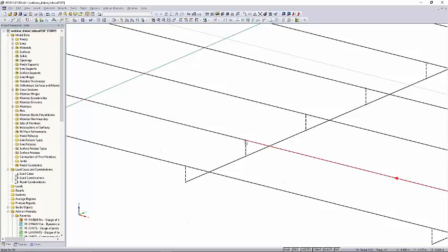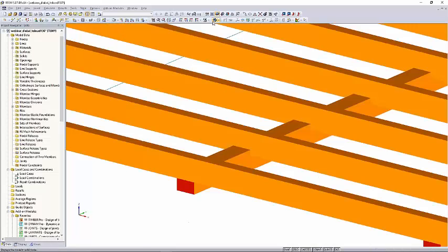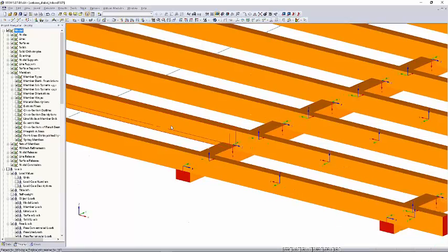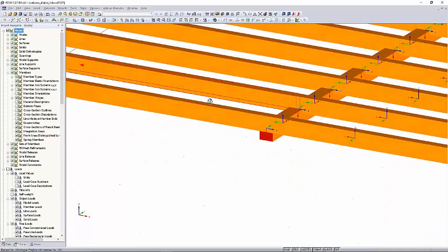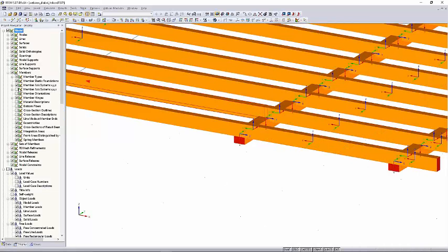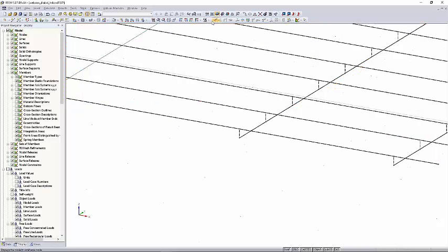In this case, I will decide, okay, the rafter, if we look at the rendered model again, has to turn around this axis. I will display the elements one more time and therefore go to where the members are and display the members axis, and I want to rotate the rafters around the local axis Y. Okay, that out, that on here.